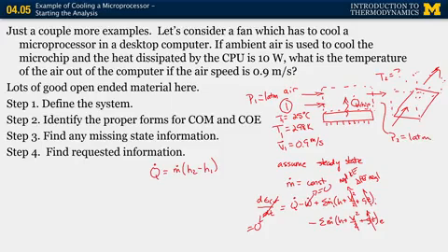Now, often people will have a kind of knee-jerk response to say it's a constant pressure process. That's overstepping your interpretation. We don't know that it's a constant pressure process. We just know that at the entrance and at the exit, we're going to end up on the same isobar. Okay, so we have a fully defined entrance state. We think it's air, so you know it's not condensed.